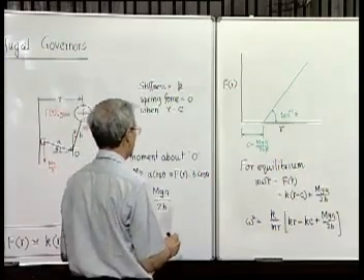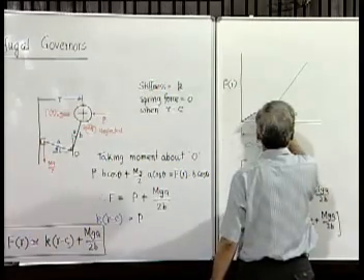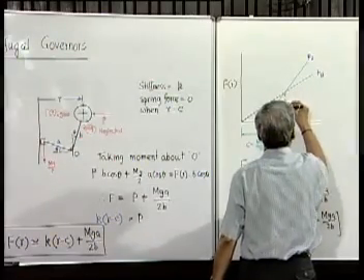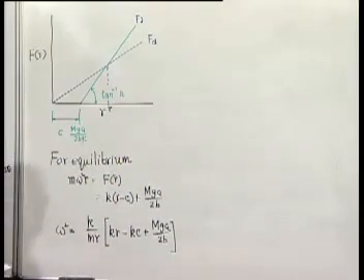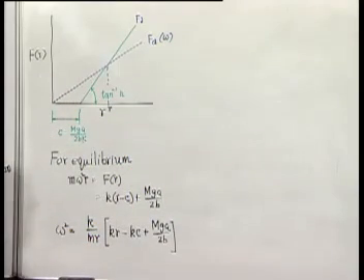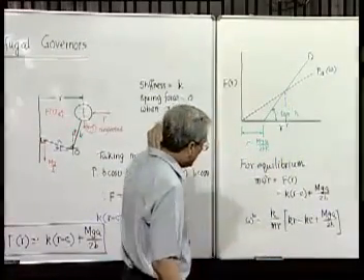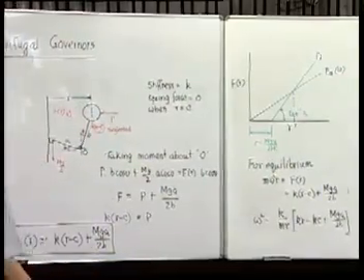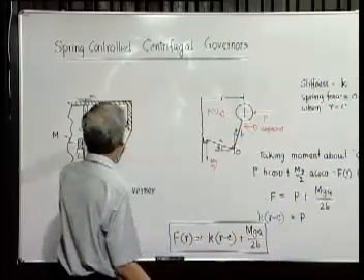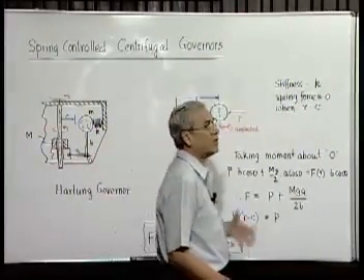So therefore, we can find out what will be the equilibrium speed very easily, because this will be your m omega square R, and obviously this is the equilibrium speed, equilibrium radius R for a particular value of omega. As the speed increases, R increases, and it is quite obvious. Now you see, there is a possibility, because this quantity, that is the original length of the spring, stiffness of the spring, the length of these bell crank levers A and B, these are all adjustable things which we can control at our will.